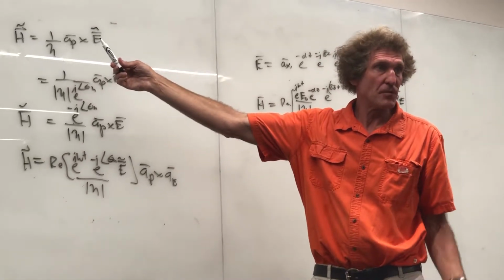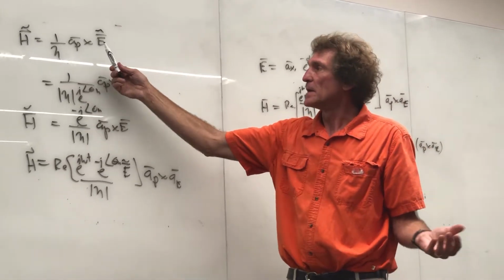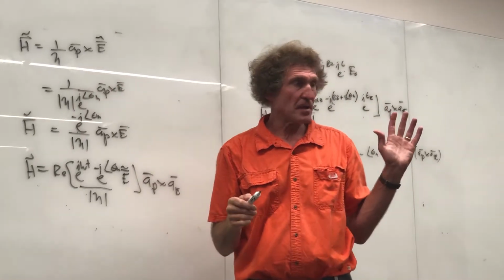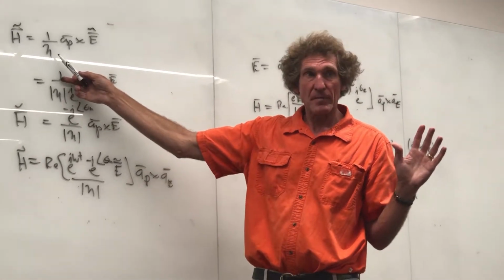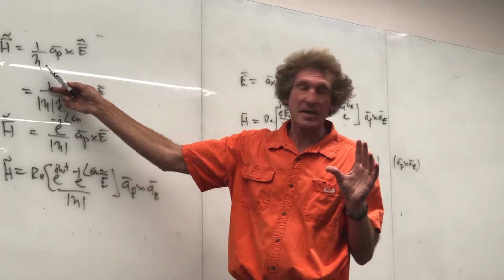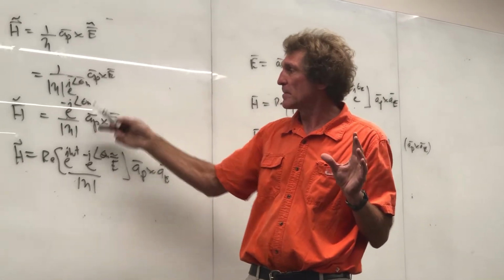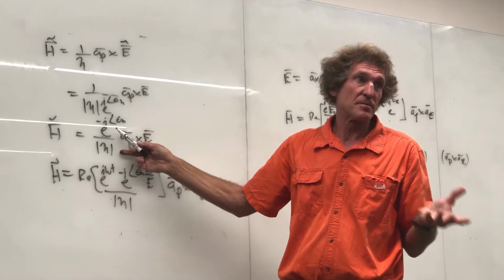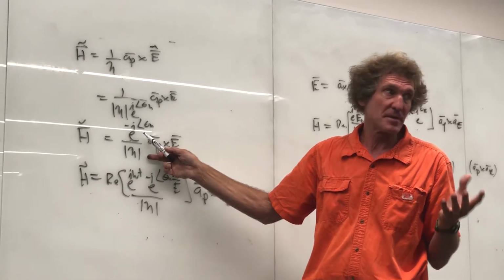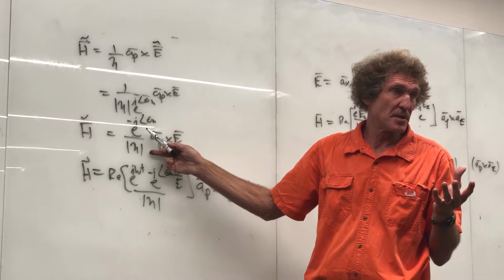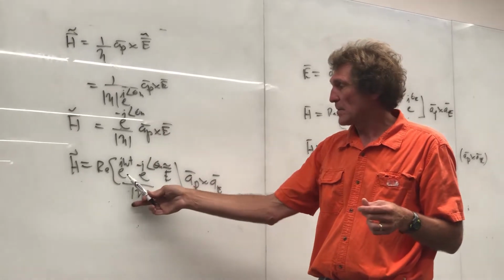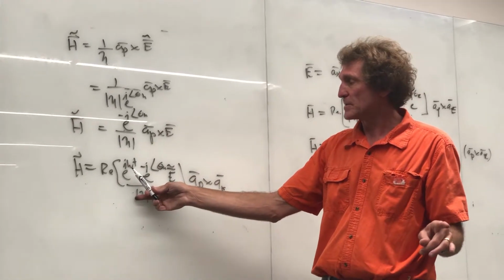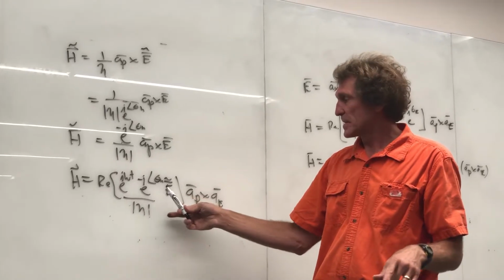That's the only thing: if you have an E field in phasor form, now you get the vector sense for the H field here. The eta here has a magnitude and a phase angle. When the phase angle comes up top, it changes polarity. If it's 30 degrees downstairs, it's minus 30 degrees in the numerator. Then you have to multiply by j omega t times this times the E field.